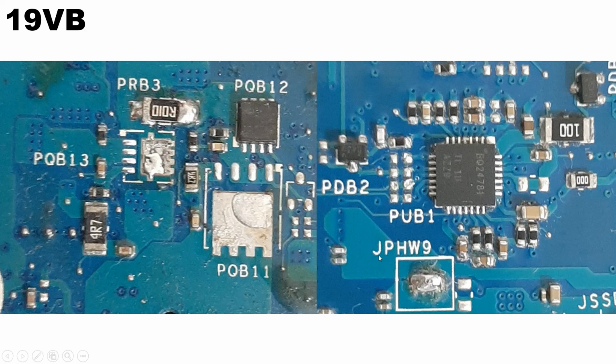Next, see, in the motherboard, the BQ24781, this is the charging IC. It looks like this. Okay, here is the bottom part, and here is the top part. See, in the bottom part, here is the supply. This is the diode actually. So battery and normal V-in voltage will enter here, and through the 100 ohms resistor, it will enter the charging IC. So this resistor should be there. You must check this one before doing any other R&D in a no power on case.